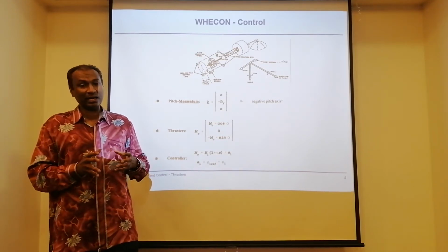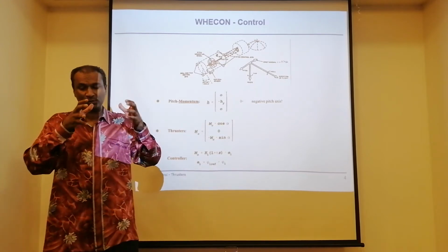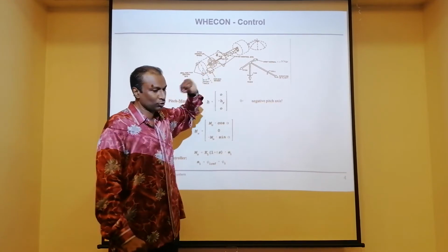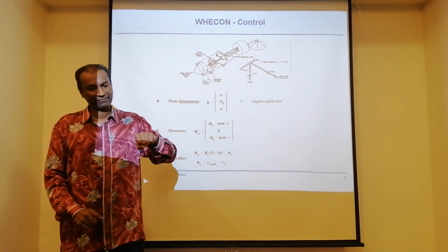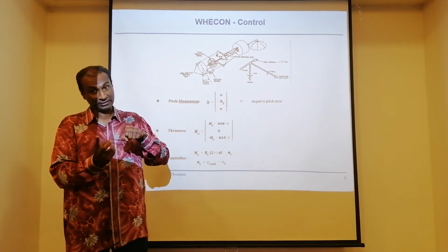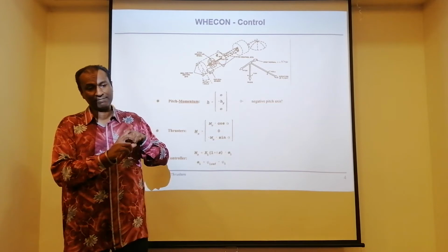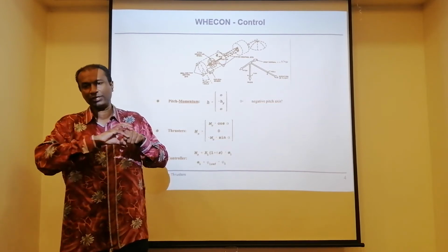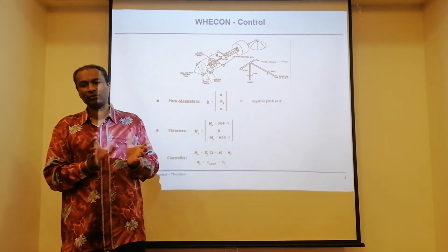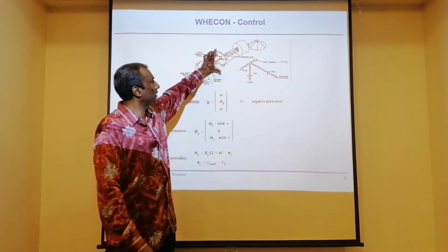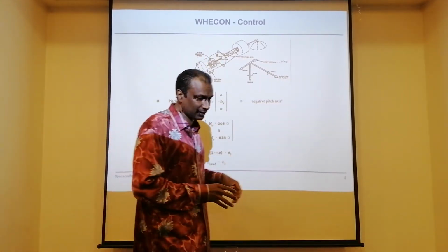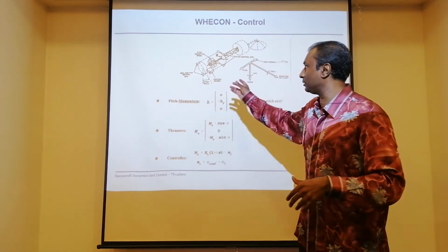That means I give a negative torque so that the wheel speed is going to slow down. In order for me to get a negative torque, let's say this is a cylindrical body, I fire the thruster system. I fire, let's say, 1 Newton up and 1 Newton down. This body is going to rotate. So depending on a positive or negative rotation, you can have a rotational motion in order to desaturate the wheel. So this is basically a thruster system which is in charge of desaturating the momentum wheel.